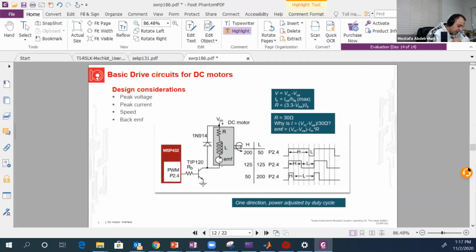Okay. Now, how do you interface the motor to the microcontroller? The problem is that this motor needs between 0.5 to 1 amperes to run. You need to provide very high current, between 500 milliamperes and 1 ampere, in this coil so that it has enough force to rotate.